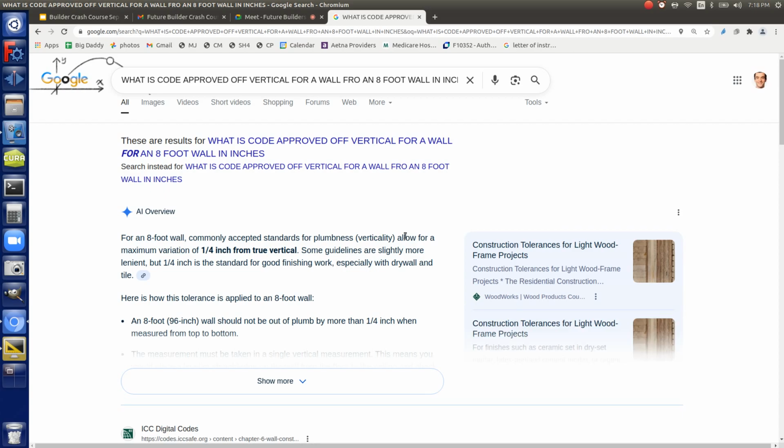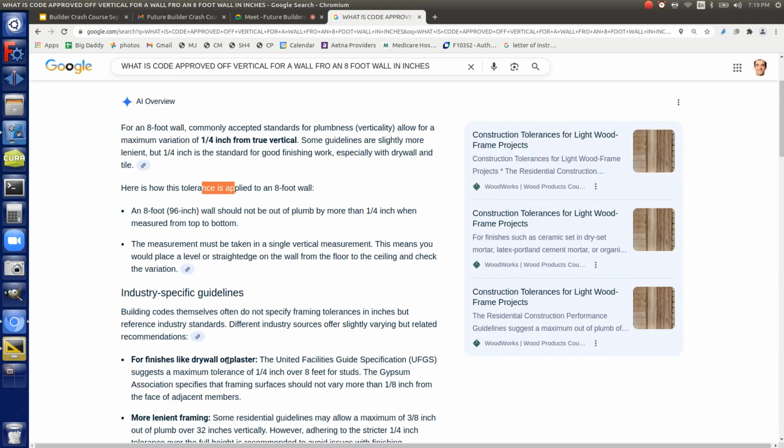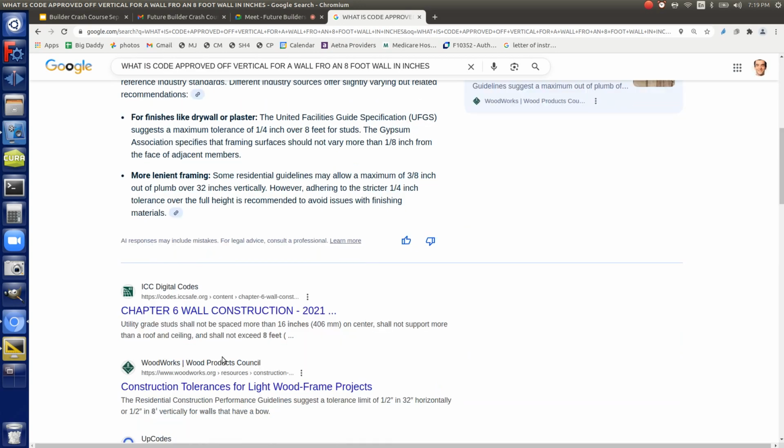Some guidelines are slightly more lenient, but 1/4 inch is a standard for good finish work, especially with drywall and tile. That's industry-specific guidance. So I'm assuming that in light wood frame construction...